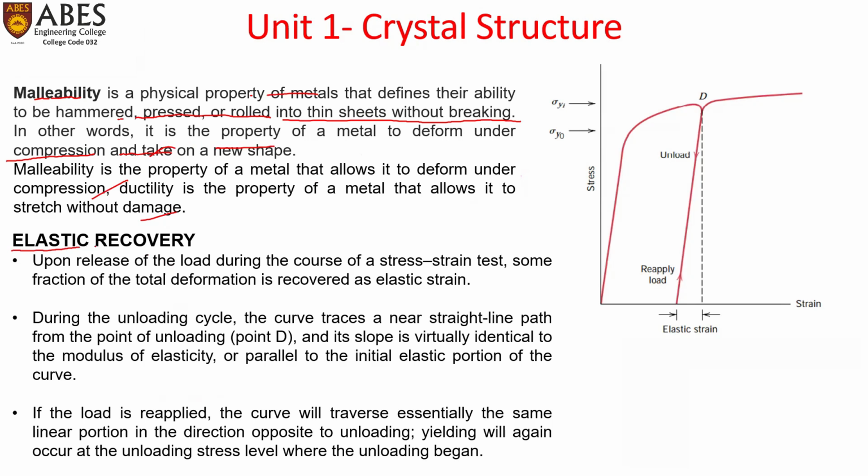Now, there is a term elastic recovery or elastic strain recovery. This is also important. Upon release of the load during the course of a stress strain test, some fraction of the total deformation is recovered as elastic strain. If we unload the material, the loading gets removed, and there would be a recovery of strain that is called elastic strain. During the unloading cycle, the curve traces a near straight line.